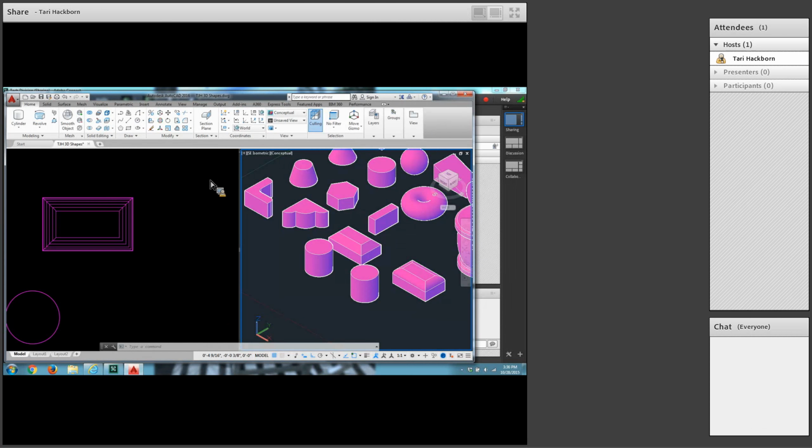Okay, chamfer, the hard one. Click distance down here, type 1/16 and enter. Enter again for the second distance. Pick the edge. I don't have to pick next because the top highlights. Of course, the bottom highlighted too. Do the 3 enters. Pick this edge again and enter. It didn't work. Okay. I don't think I got it. Okay, let's go through that again.